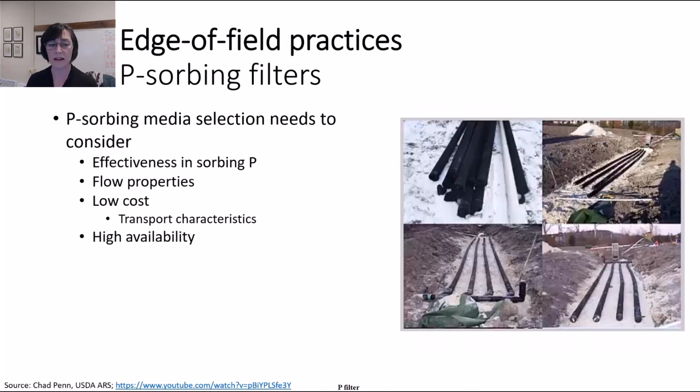Which plays into our next factor. You want to consider cost, and cost involves the transport factor and the availability. So for example, that MDR in the last picture, I wouldn't recommend everyone use that everywhere because that was from a mine drainage treatment facility in Pennsylvania. So that'd be very expensive for someone in California to try to use that material. So obviously cost plays into your selection criteria.